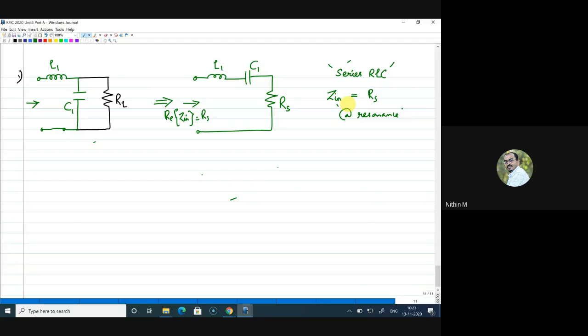All right, Nikhil. So what I am telling is, I had a resistance RL, and that is now RS. And by relation, I can prove that this RS is smaller. That means I could down convert, or transform the resistance value to a low number. But for doing the transformation, I have introduced this L and C element. Now, since I have introduced this, what I need is only a real part, right?